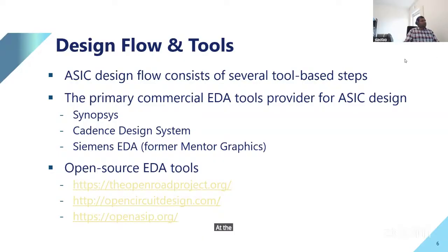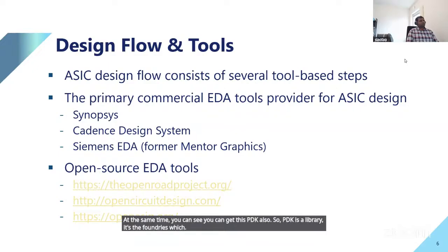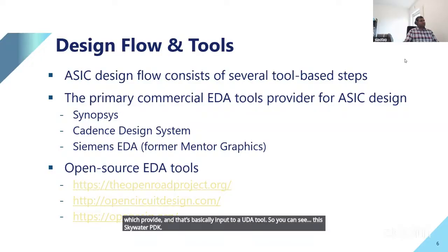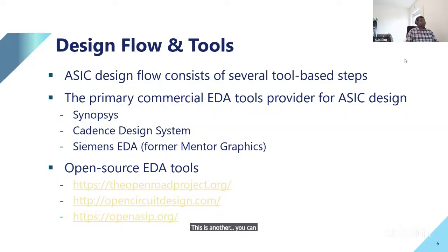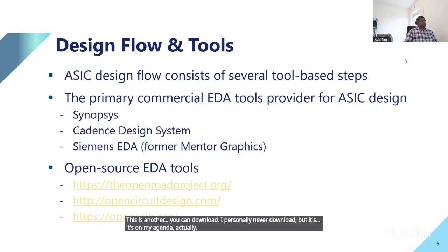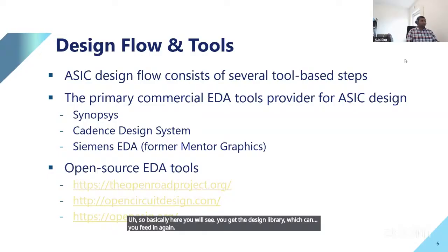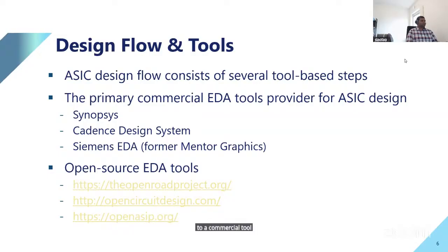At the same time, you can see you can get the PDK also. A PDK is a library which the foundries provide, and that's basically input to an EDA tool. So you can see this Skywater PDK. This is another one you can download. I personally never downloaded it, but it's on my agenda actually. So basically here you get the design library, which you can feed into a commercial tool or open source tool, and you can design your stuff, implement your stuff.